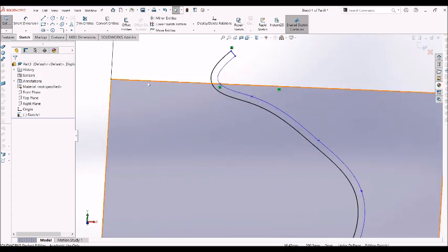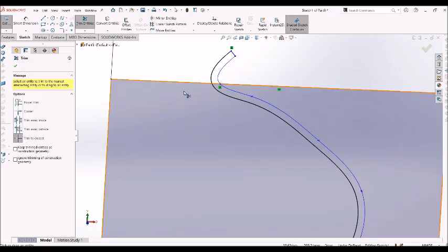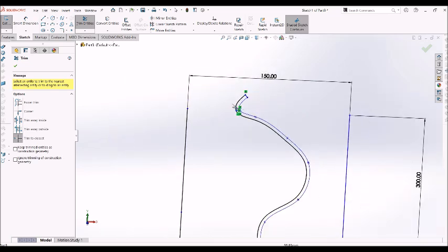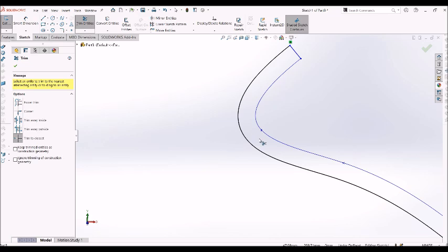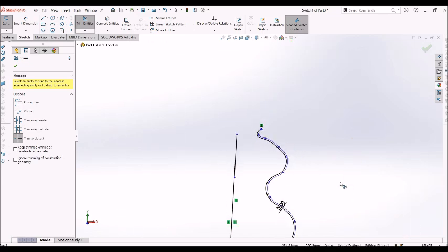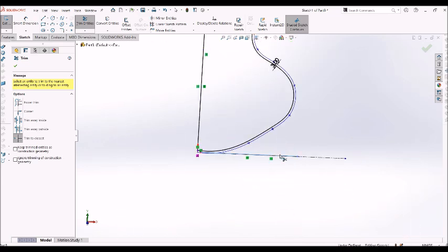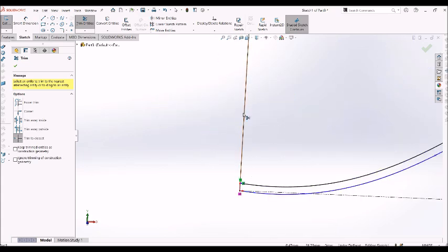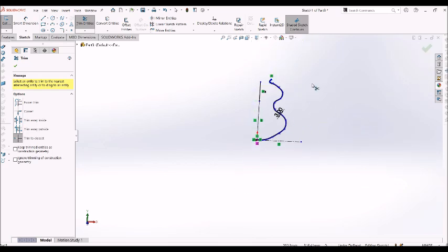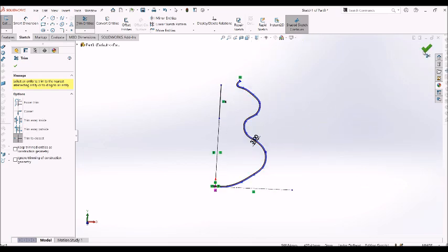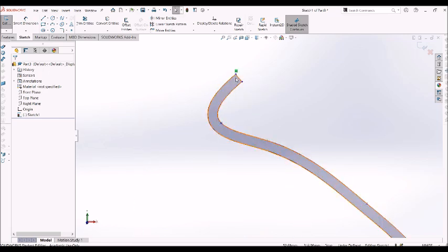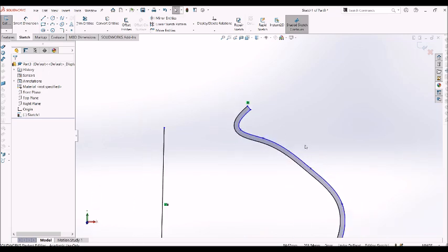What I'm going to do is use our Trim Entities button, and trim away the lines we don't need to give us one big shape instead of loads of tiny shapes. You sometimes need to zoom in and zoom out when you're doing this, just to see what you're doing. And you know it's a closed entity because it goes that grey blue colour when it's a closed entity.